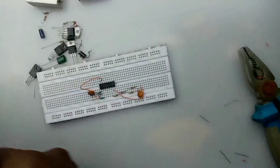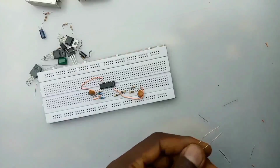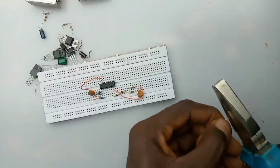Mount 0.01 microfarad and a 20 k ohm resistor between terminal 9 and the ground, which is terminal 8.